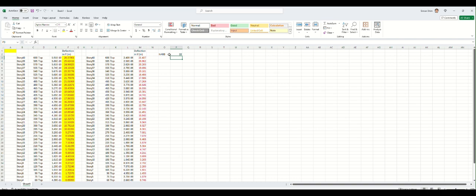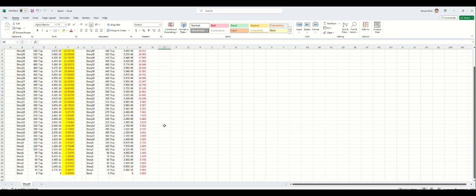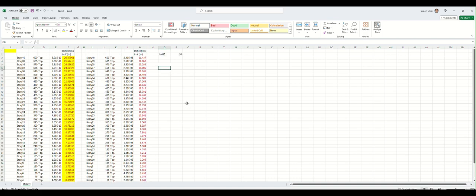So we're going to continue until we meet it, with the top wall at 18 inches. But since this wall is already thick, we may think about a better, more efficient way to increase the lateral stiffness instead of just increasing the wall thickness, which is more material and not efficient because eventually it increases the foundation wall reaction. So this is iteration.